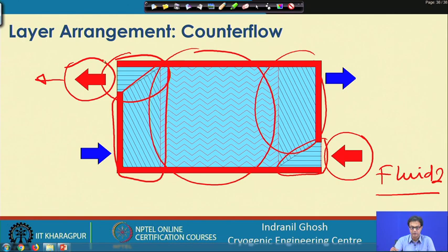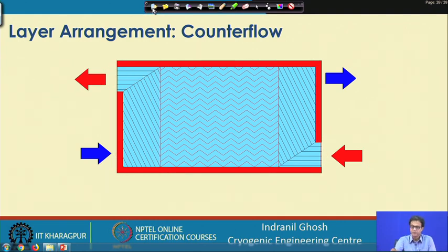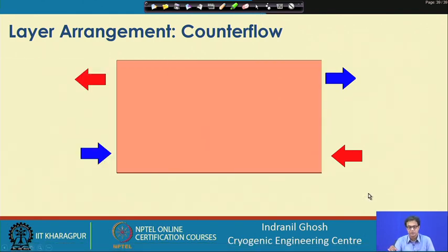1, then we have a separating plate, then we put another layer for the second fluid 2, and then, as usual, you can understand that we have to put a separating plate. So, we will have this separating plate. This is now constituting one complete layer of fluid 1 and fluid 2 with the cap sheet at the bottom, and we have a separating plate on top of it.